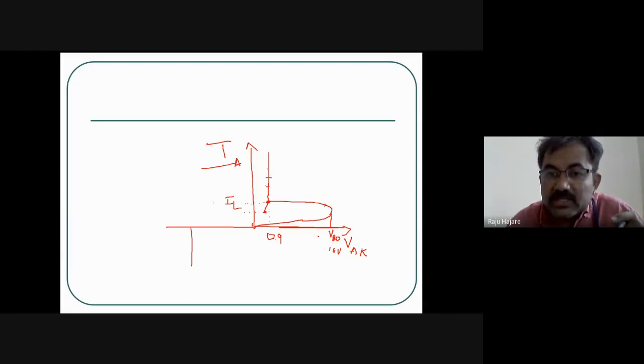Even for 0.05 volts, a very small negligible value, millivolts, it makes a big difference in the current rise. So the current reaches some value here for maybe a 0.1 volt difference on the x-axis, maybe 0.9 to 1 volt variation. I am getting this vertical line, and I call it the forward conduction region, or forward conduction mode of operation.